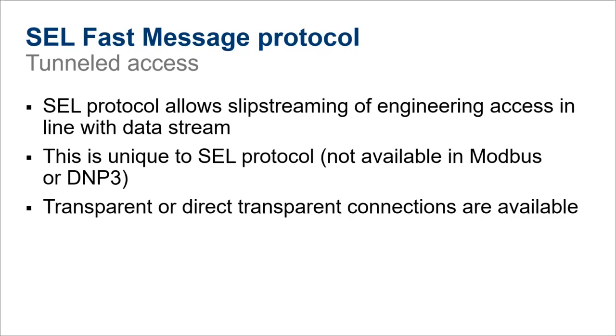In the case that you need to do the transfer like that, you would select a transparent mode for one where you want SCADA data to continue, or a direct transparent mode where you want to pause SCADA data to focus on the terminal session. If you're using a modern connection like the RTAC, this is all managed automatically through the SEL server connection, so you don't have to worry about transparent and direct transparent in most cases.